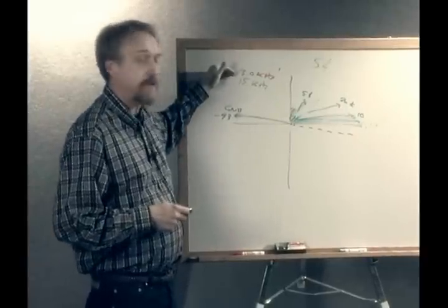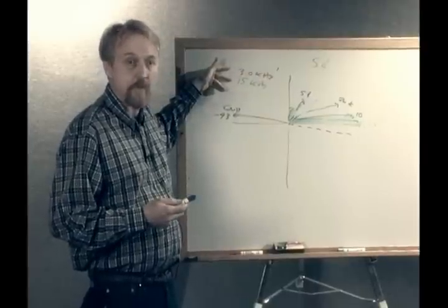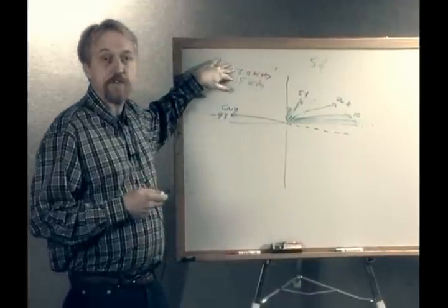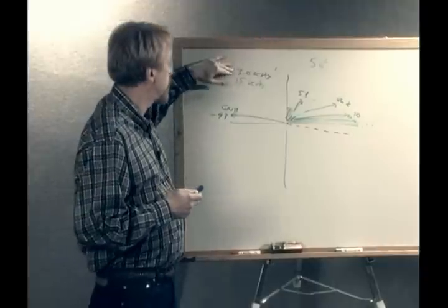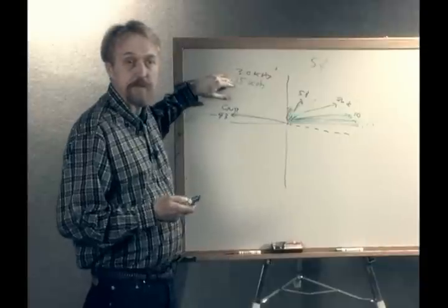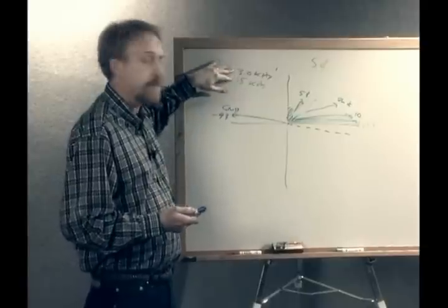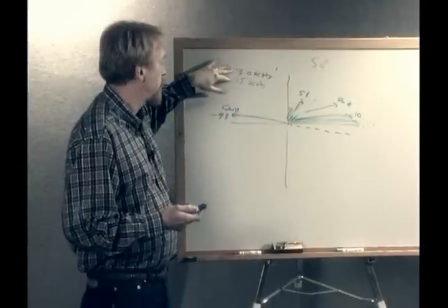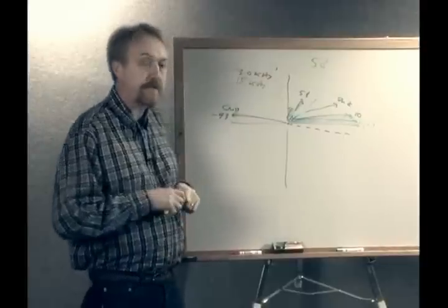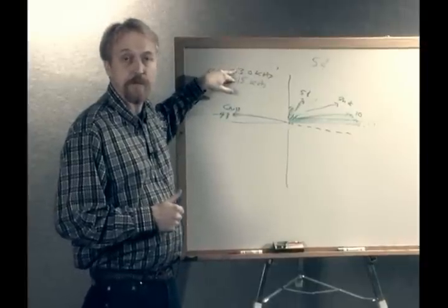But in addition to that, the DFX can process both frequencies of information simultaneously. And the way we do that is by first processing them in a conventional fashion. So for example, we'll do discrimination at 3 kilohertz by conventional means. We'll also do discrimination at 15 kilohertz by conventional means. And then our microprocessor will compare the results. And there's a couple of ways that we do this. The first way is to look at the strength of the signal at either of the two frequencies and to pick the stronger of the two.